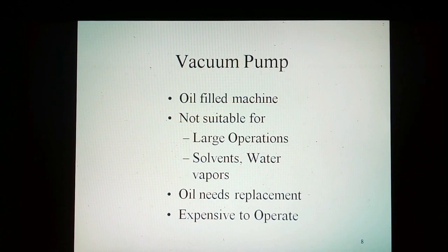In this model, an inbuilt device, known as gas ballast, is provided, which effectively checks to a large extent condensation of the water vapor, which otherwise would not only have contaminated the oil, but also diminished the performance of the pump.